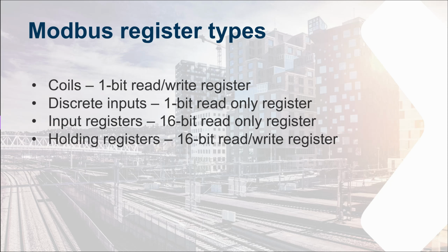And then we have holding registers, which are 16-bit read-write registers. Holding registers can be used for all the same functions as the other 3 registers. For read-only use, you just need to not write the register. The holding register is the most used register in the Modbus system.